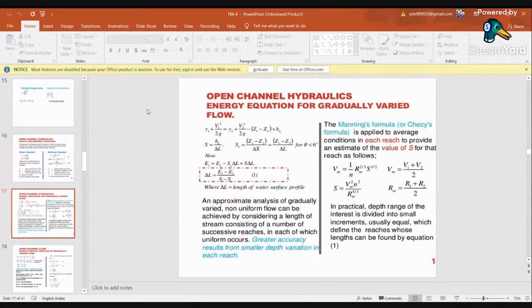So hydraulic depth and hydraulic radius are two different terms in open channel. For hydraulic radius, we divide area by wetted perimeter, and for hydraulic depth, we divide area by top width.